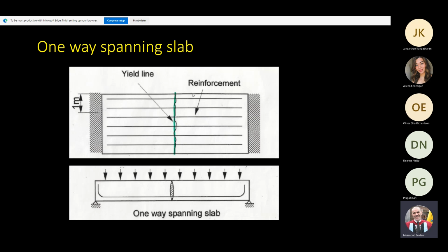Why in the middle? Because the supports are at the ends. I mentioned the word earlier. I don't know how you paid attention to it. Curvature, maximum curvature. Yeah. So when your beam curves, the maximum curvature is in the middle. It just happened that the maximum bending moment and the maximum deflection are in the middle. But it's not always the case. You don't always get the maximum moment and the maximum curvature and the maximum deflection at the same point.